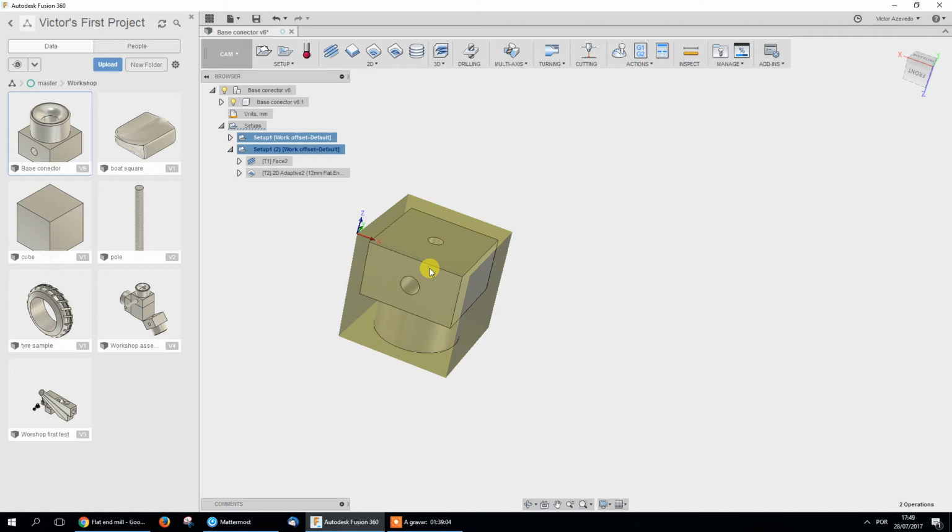Okay? That's why you have problem with that hole. No. Because, but this block won't be against the vise. I'll use spacers. Tem umas paralelas que fica espaçado e tem espaço por baixo da peça para furar. You have space. If you use spacers, you'll have space between the part and the vise for the drill to go through. Okay, it doesn't touch the vise.